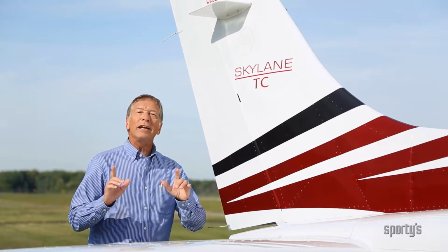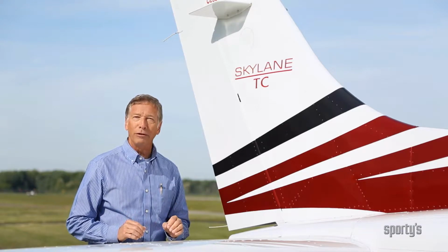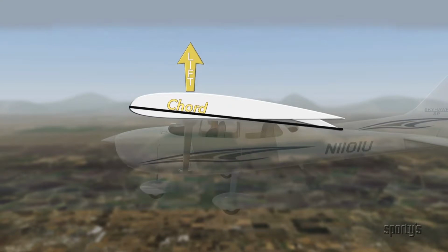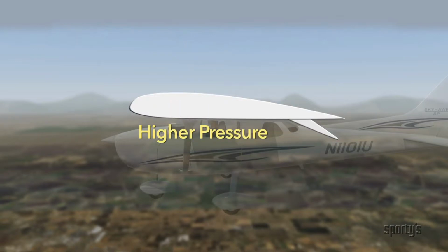Well, let's take another look at what happens when the ailerons are deflected into the airflow. The deflected ailerons change the wing chord of the outboard part of the wings, which in turn changes the lift of the wings. Also, the down aileron is in higher pressure while the up aileron is in lower pressure.